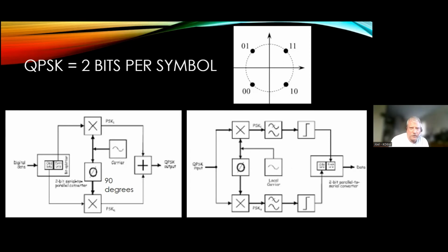And so you end up creating a waveform in a constellation pattern, which is based on the 2 bits. In QPSK there are 4 quadrants, 2 bits per symbol, and there's 11, 00, 01, 10. If it's representing one of those, the signal points in that direction. For every 2 bits that go through the system, you're clocking it at a very specific rate, and that's your symbol rate. That's how fast you can move the data through the system. As you increase the symbol rate, that carrier waveform flips around to represent whichever 2 bits are being represented. At the end of the day, you'll see these concentrated 4 dots on the waveform trace, and those are the bits being modulated.